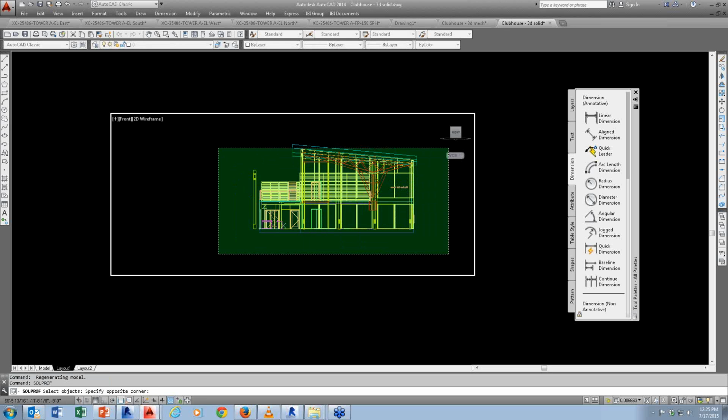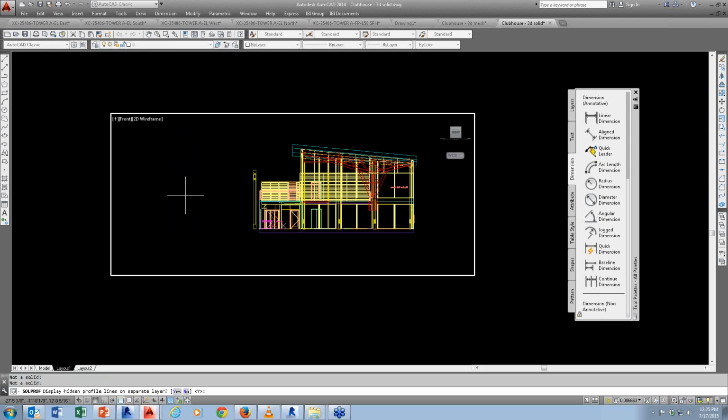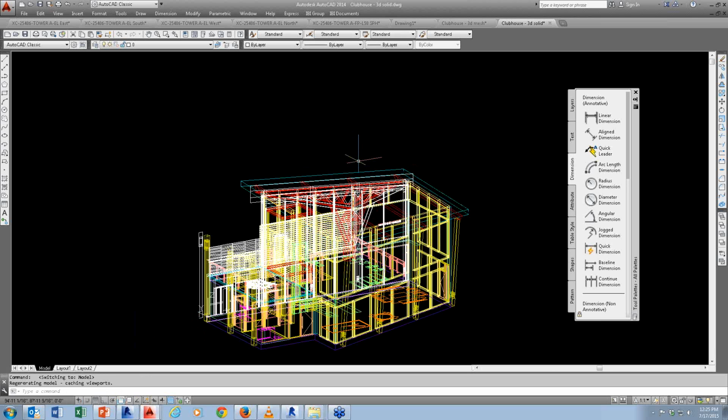And what you have to do is just select all this object. And then it asks, do you want to separate the layer, the hidden lines? Let's say yes. And solid profile object, project to the line, yes. And do you want to tangent? Yes. Just say yes, yes, yes. Now, what's going to happen is that it's going to create a 2D.